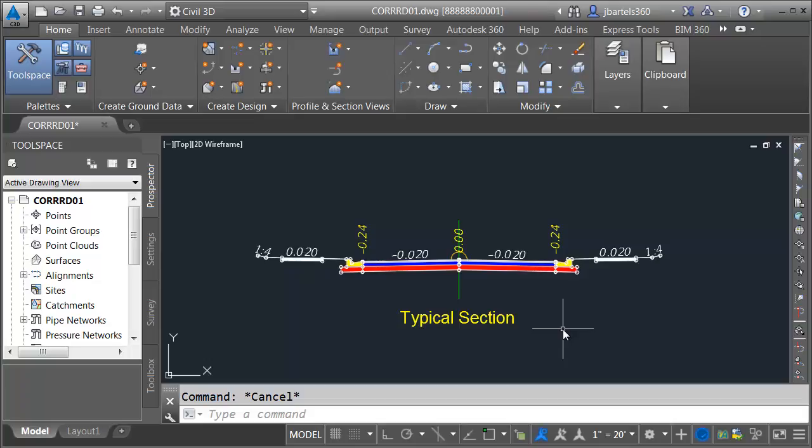In this session, we're going to lay down some foundation before we get into corridor modeling. On my screen is an example of an assembly. The assembly is one of the three components necessary to build a corridor, the other two being alignment and profile. The assembly represents the typical section of your design. The actual assembly object is this vertical line right in the middle.